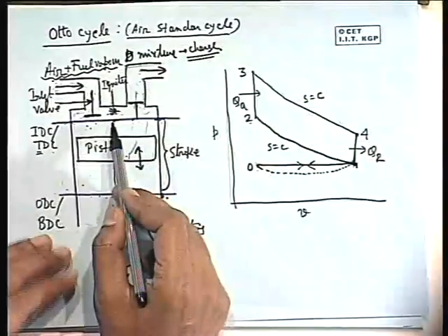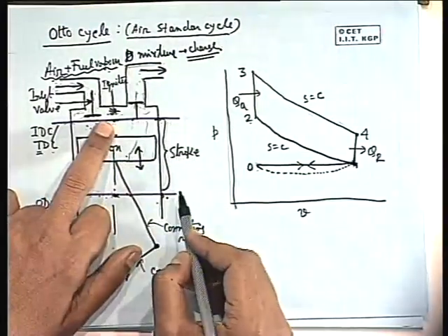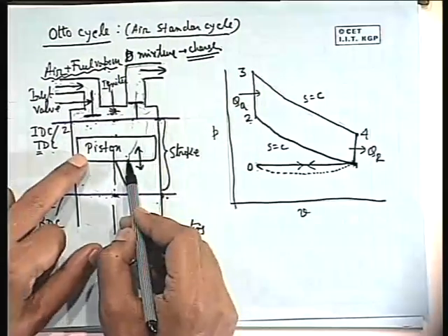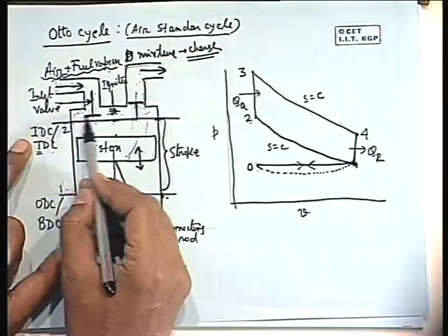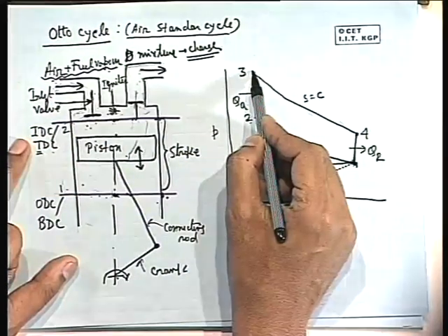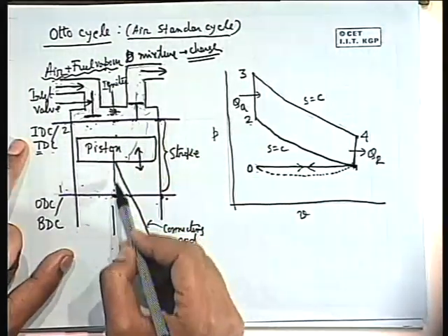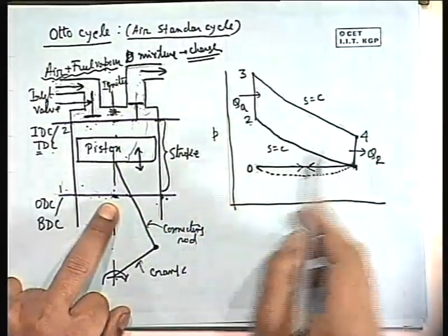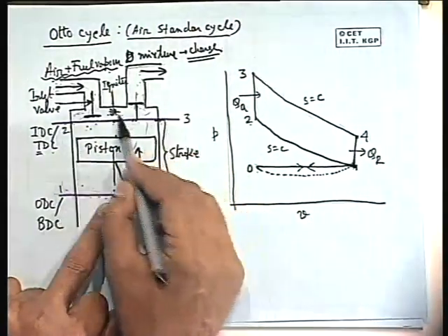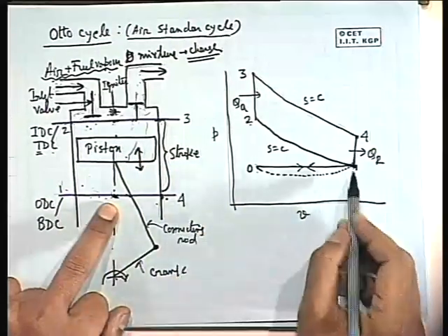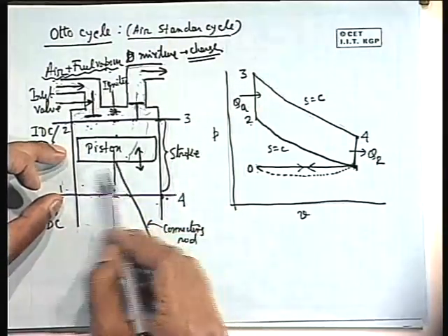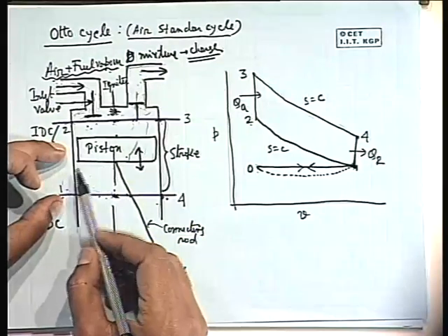Now this is a closed system cycle, which is first isentropically compressed, then after isentropic compression to a volume 2, that means here I do this way 1, 2, then at this point, keeping the piston fixed, we bring a source and heat it to a temperature 3. You understand? Then from 3, we allow the piston to come down or come out, so that there is an isentropic expansion. 2 to 3 is the heating. Then when it comes to 4, we remove the insulation, we keep a heat sink and make a heat rejection process at constant volume.